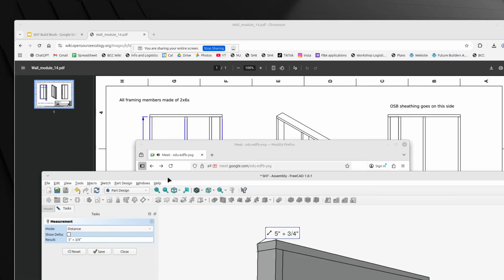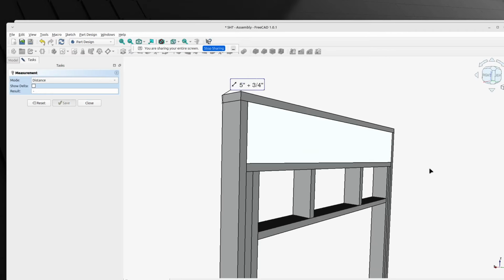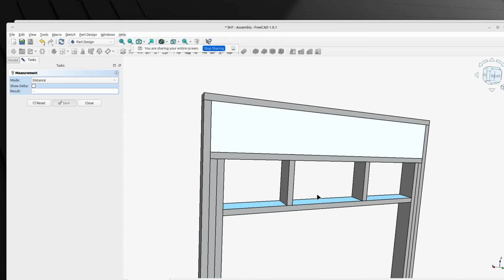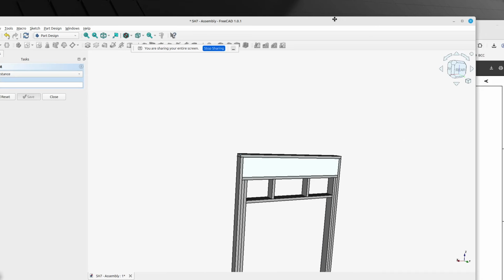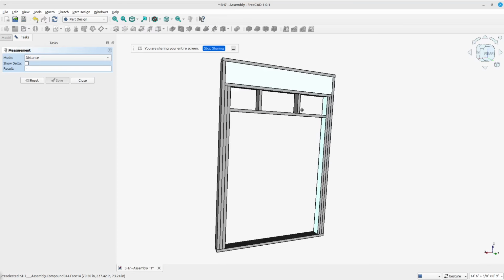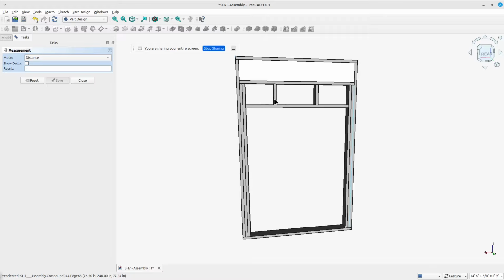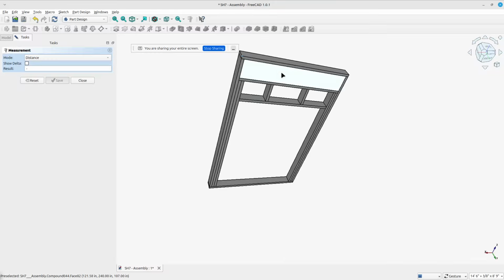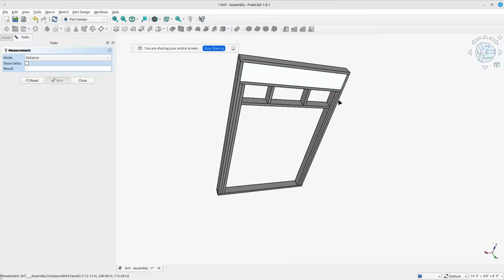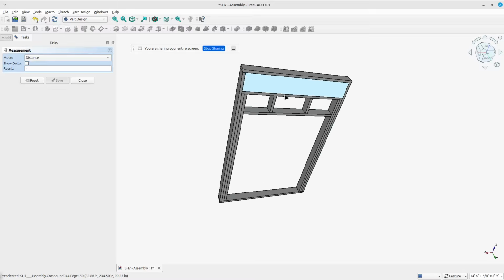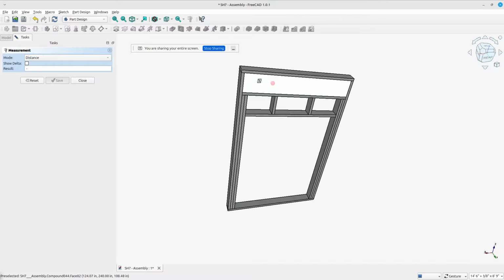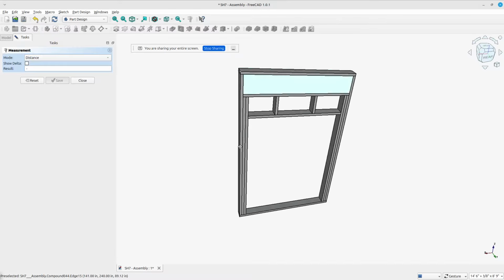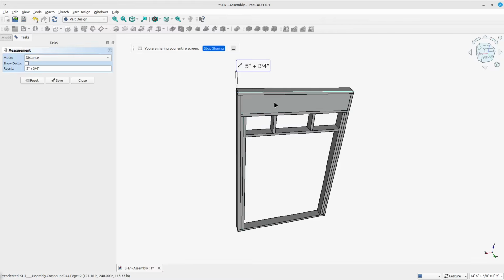So if we look at the file, we're talking about the door header. Did you follow that, Richard? I'm not sure what you mean by infill. So the door structures are made like this, where there's side framing, and there's this header, the wood that I'm pointing to, which bears the loads. It's a load-bearing header, so that's why it's vertical on edge like that, to support all the weight of the roof above it. Now, in our case, I believe that's a 2x12 piece of lumber.